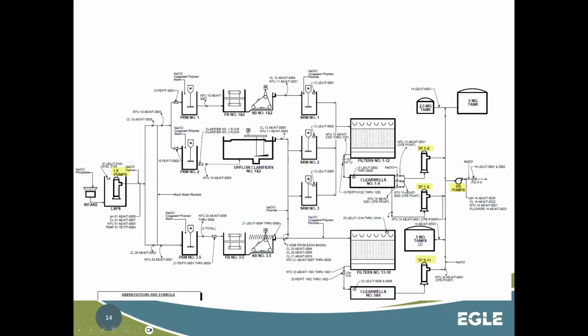Then we go into our secondary. We'll have another coagulation, separation, separating out. Let me back up. This is where in your clarifiers, your settled sediments, also sludge. These are where your sludge pumps would be. This is taking that sludge from that settled clarifier and putting it into some sort of tank storage for treatment, underground, usually away from site.